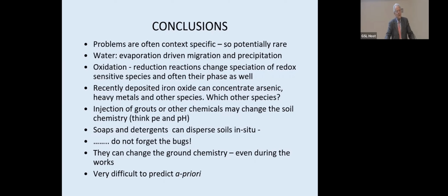So if the water's pH neutral, then the stainless probably won't be attacked. It was a combination of acid and something that strips the oxide film off. And as you say, most soils and groundwaters are relatively benign. That's so we don't see problems.